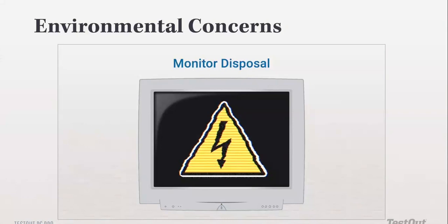These monitors have very large capacitors inside them. The same way we talked about the PSU, the power supply unit, which stores electricity even when power is taken away, these monitors also have capacitors as large as those of the power supply unit that can store electricity for a very long, extended period of time. So you can find electricity stored in this monitor for even 2 years.